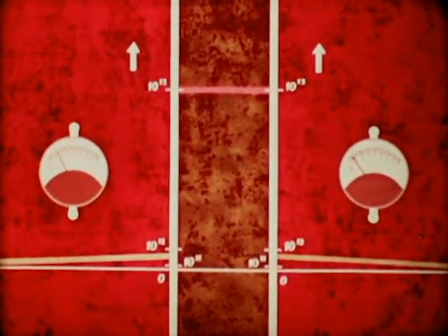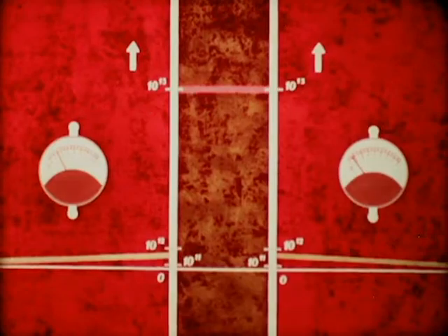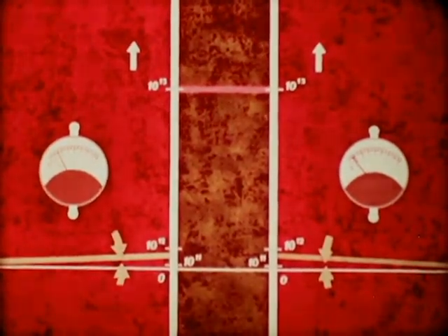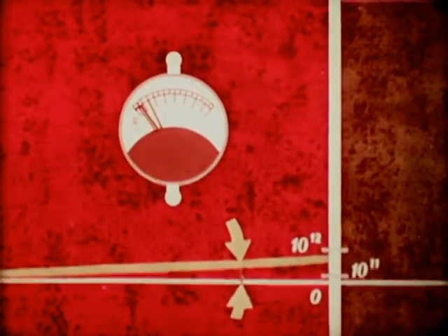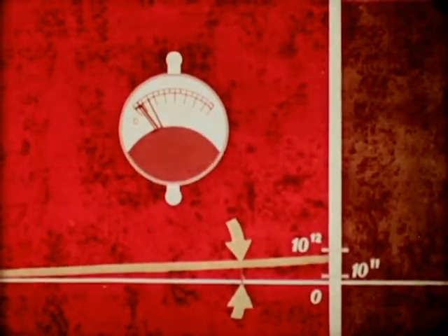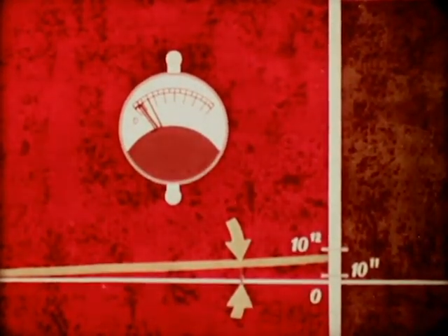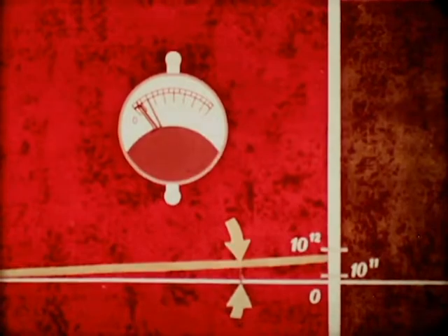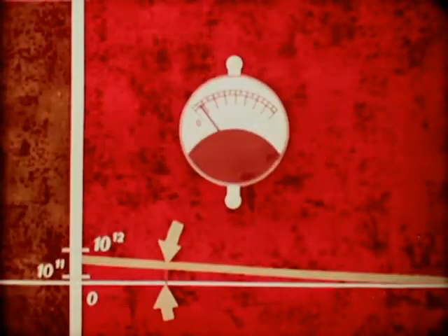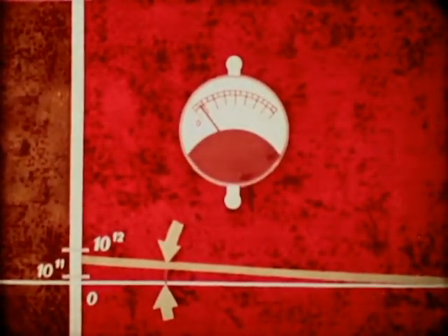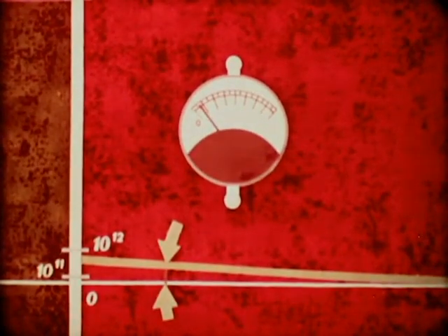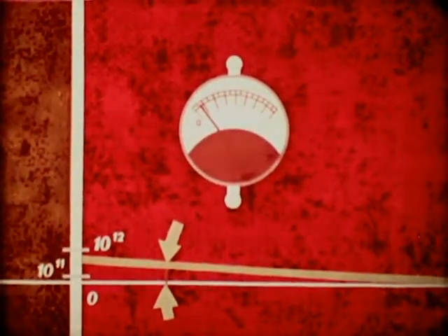Only a proportion of the current flowing in the emitter circuit corresponds to the angle formed by the concentration graph of the electrons in the emitter. The rest is due to surface recombinations. Similarly, only a proportion of the collector current corresponds to the angle formed by the concentration graph of the electrons in the collector.